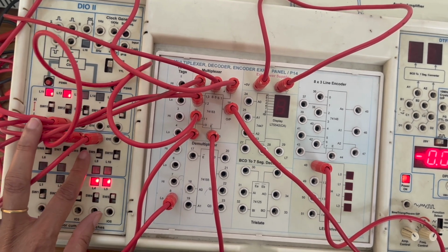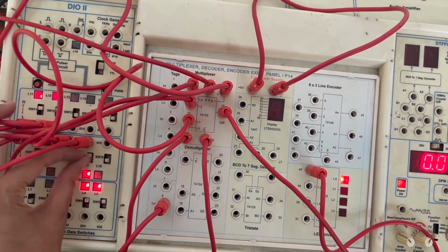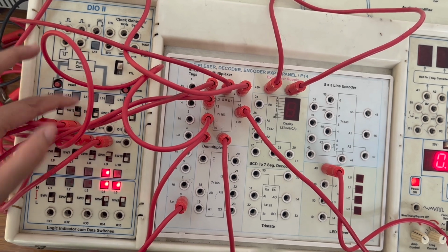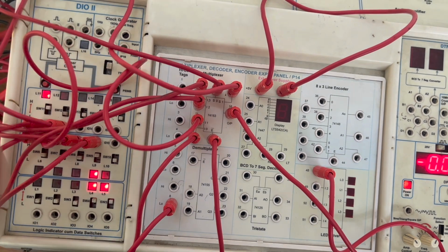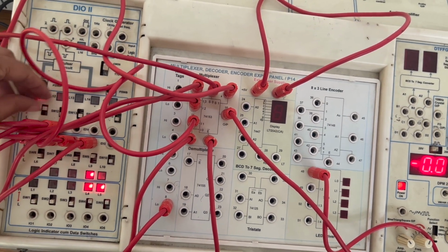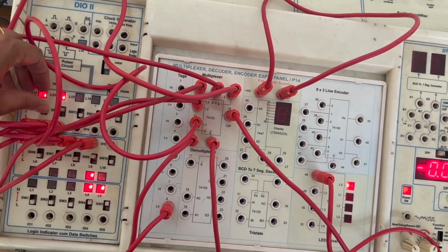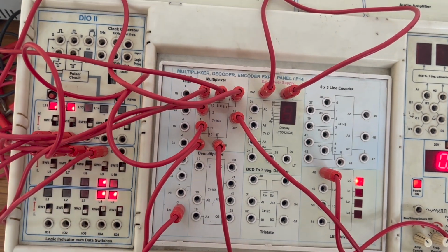So how this multiplexer circuit was, 4:1 multiplexer, that is one of the input is transferred to output depending on the value of the selection line. When selection lines are 0, 0, it is responding to first switch. 0, 1, it is responding to second switch. You can observe the switch position. 1, 0, it is responding to third switch, and 1, 1, it is responding to last switch. This is how 4x1 multiplexer works.